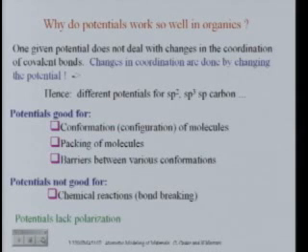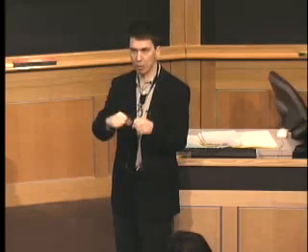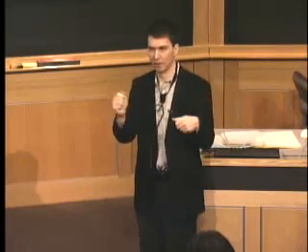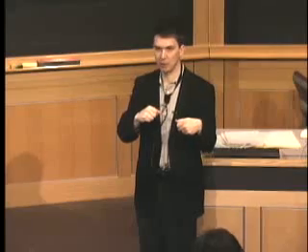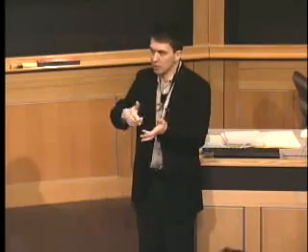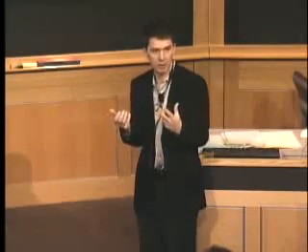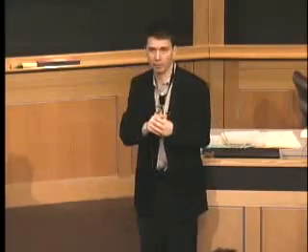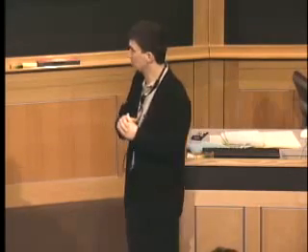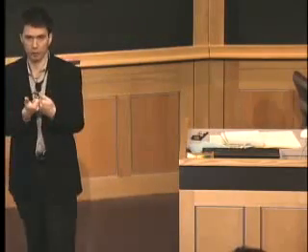So you can describe very well things like bending of polymer chains with potentials. And the reason is, it's essentially a local effect. You're always bending the same bond, whether that's in polyethylene, or whether that's an sp3 carbon in something much more complicated, it's essentially the same bond you're bending. So you can parameterize it very well, and it's pretty much always the same, independent of what's far away from you. But this also means that there's stuff that it will not work for.